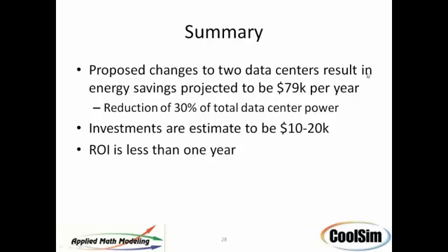Okay. Has CoolSim looked at raising the inlet air model temperature above 65 degrees Fahrenheit, say 75 degrees Fahrenheit, and if so, what were the findings? I didn't chase it too high in this case. The customer didn't want me to, but it's easy enough to do. You can just put a different delta T in and have a look at it. I have seen them run as high as 70 degrees before and be fine. If you can get the airflow correct, you can run them right up to 70, 75 degrees.